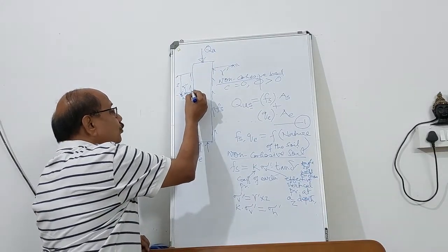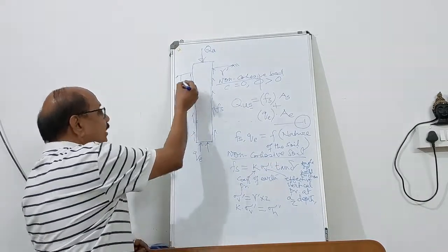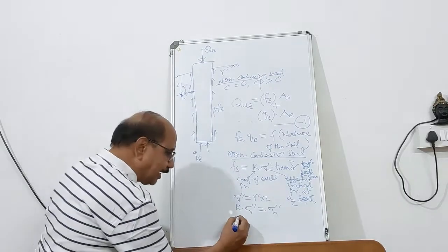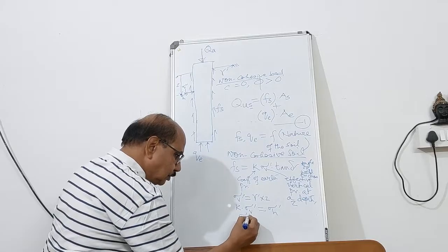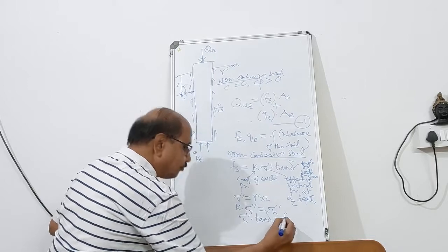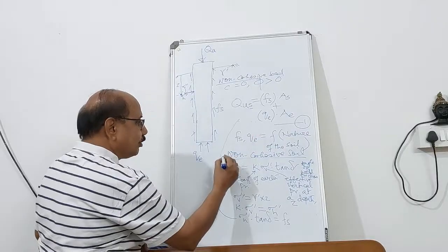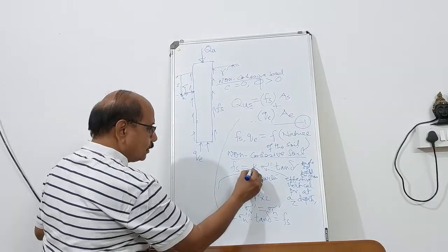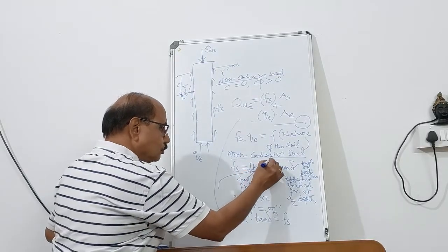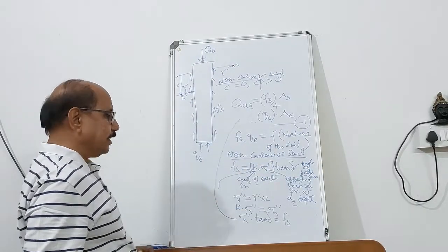Now, if you multiply it by mu, which here is tan delta, then that becomes the unit skin friction Fs. So sigma h prime into tan delta is called unit skin friction, and therefore the formula is K into sigma v prime into tan delta.